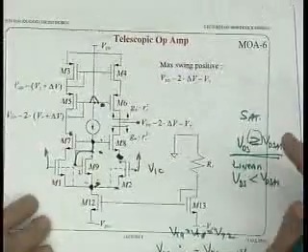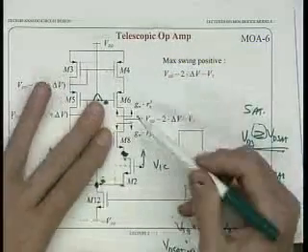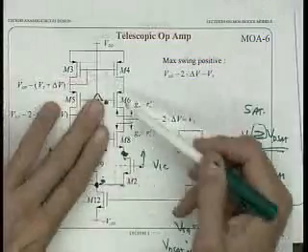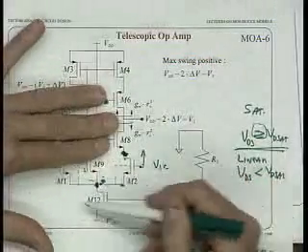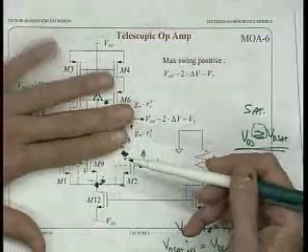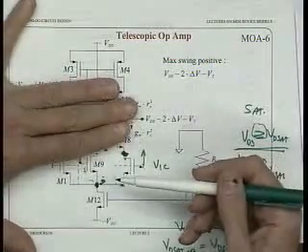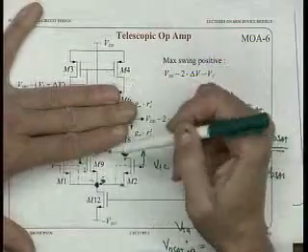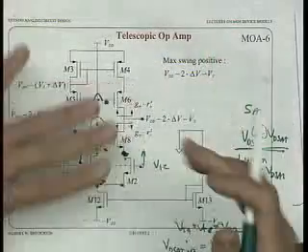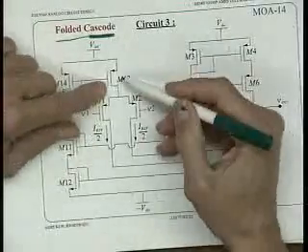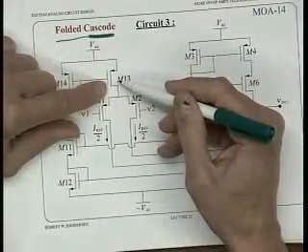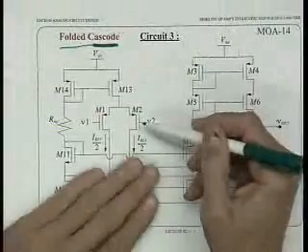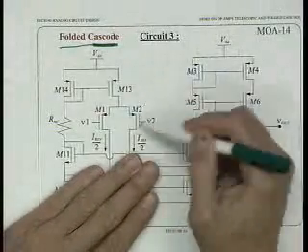So if we go back to our straight old differential pair, with a tail current source, with a current source load, this is basically what we have here if we took these cascodes out, right? See that? Okay, right? So here's the current source load, here's the two driver devices here. So flip that over. Here's the load, here's the tail current source, and here's the two driver devices. Okay? So we're back to straight old differential pair input.